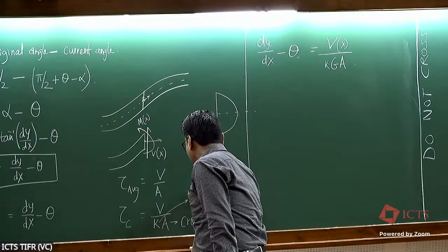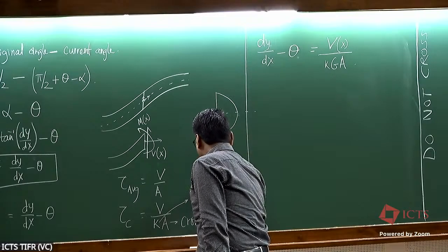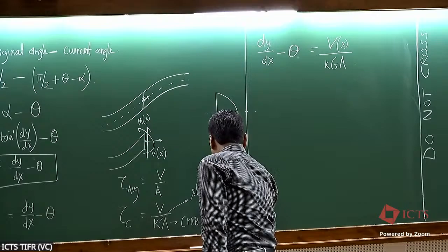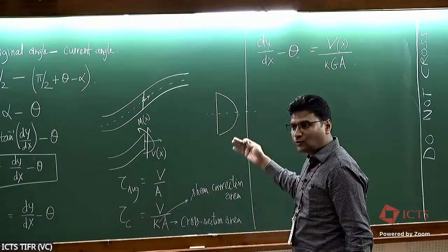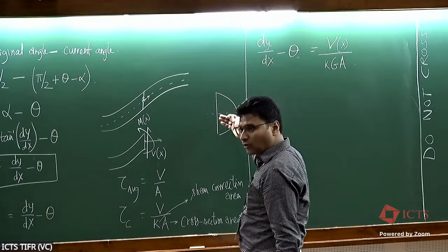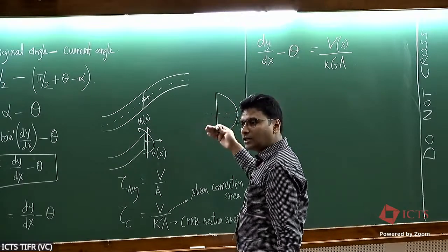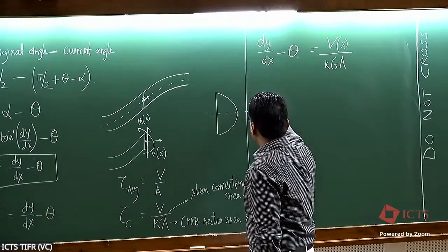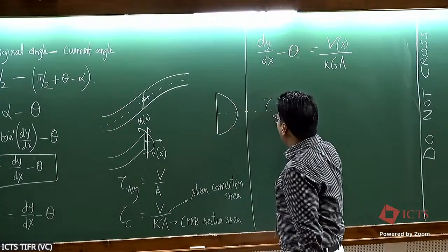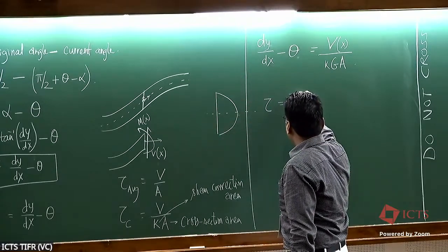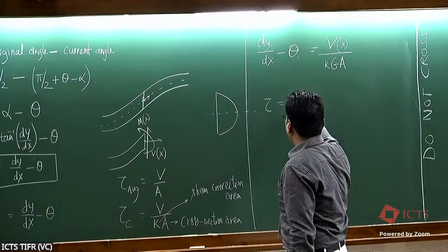So this is shear correction factor. What you really do is you have to solve the actual cross-sectional problem. And in case of rectangular cross-section, there is a strength of materials solution, which says that the shear stress tau varies in the cross-section using this strength of materials formula, VQ over IT.